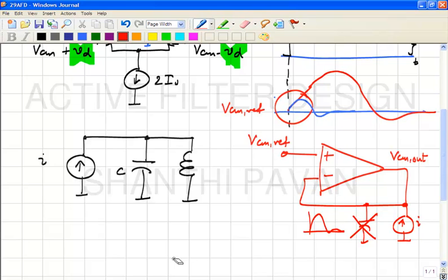Those of you for whom this argument doesn't make sense, don't worry about it. It's not important. For those of you who have actually heard this stuff before, you can interpret this as the closed loop output impedance being the open loop output impedance divided by the loop gain function. The loop gain is falling off as a function of frequency because of poles in the feedback loop, which means that 1 over loop gain must go up with frequency, right? Which basically means that the closed loop output impedance must increase with frequency, and any impedance which increases with frequency must consist of an inductive component. Is that clear? Okay. All right.